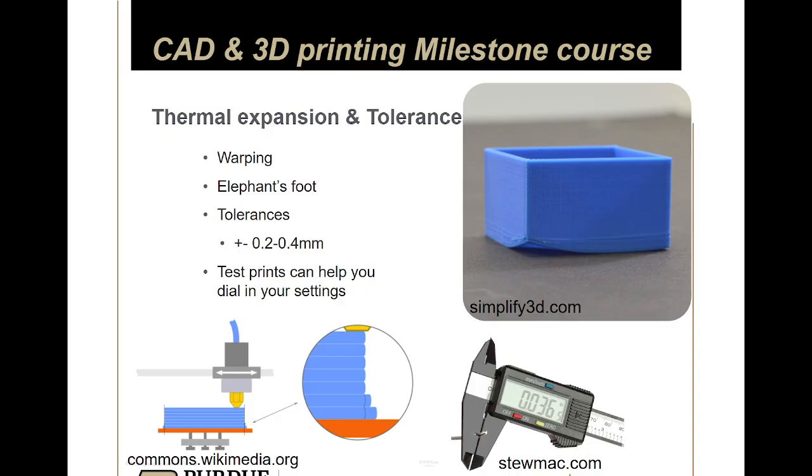One is to have a well-tuned printer, right? But that's kind of on me because I'm printing your finals. But the other thing you can do is reduce the stress concentration areas. So this box is very square and those corners are very sharp, and those sharp areas are where the stress is going to be highest. So to reduce that, you can add fillets. Again, depending on the orientation of the model, you might want to use a fillet or a chamfer, right?